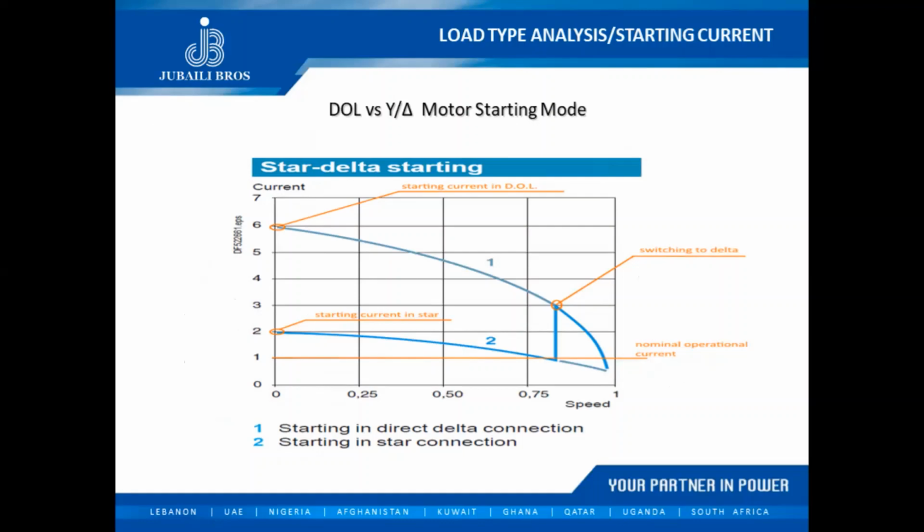You know, we have different kinds of motor starters. You know that connecting a motor directly to the power source would result in an extremely high starting current, in some cases up to 7 or 8 times the running current. For example, I'm just throwing in numbers as examples, guys, okay? So if you have a motor that's rated 5 amps running, so that draws 5 amps while it's normally running, if I connect it directly to the power source, which we call DOL or direct online connection, it could draw up to 35 amps when I initially start this motor. Okay.